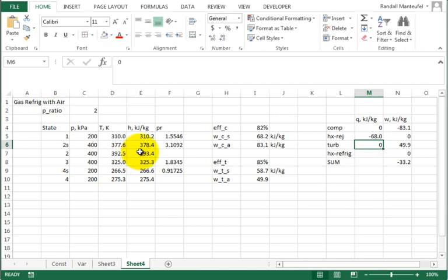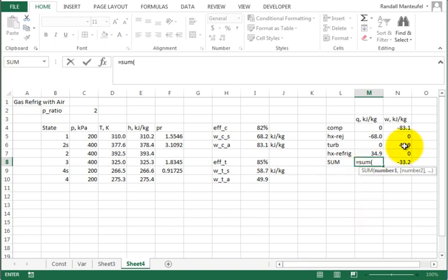So we'll transfer out 68.0 kilojoules per kilogram. And then for the refrigeration, that's energy transfer into the fluid. And so it's H1 minus H4. Makes sense? And we'll copy over this sum or just drag it or sum, just type it like that.